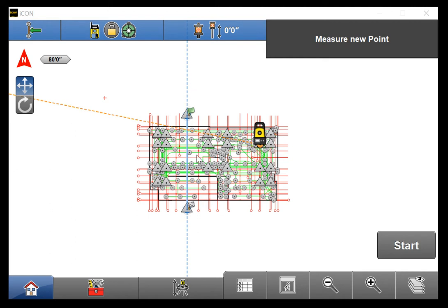Please note that this has nothing to do with north, south, east, or west. Instead, the positive and negative station values are referencing the starting and ending points of the line segment. If I flip the line segment's direction, those values will change. I will show you examples momentarily. This means that technically, you can lay out the exact center of a line segment or a specific offset to a line segment beyond the starting or ending points infinitely. To summarize, stations are the distances moved in either direction, negative or positive, depending on the location of the start point of the line segment.